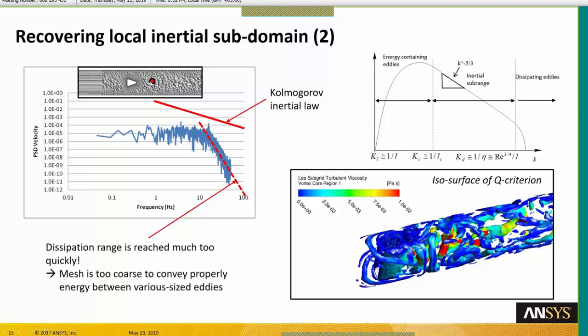So we place a probe in the wake where the grid is a bit unrefined, and then you will have this situation. You are at the probe. You are extracting, in fact, the velocity. You are plotting, in fact, the spectrum of velocity versus frequency. And what you observe is, in fact, a rapid dissipation of the velocity in this probe. So this is not the correct trend.